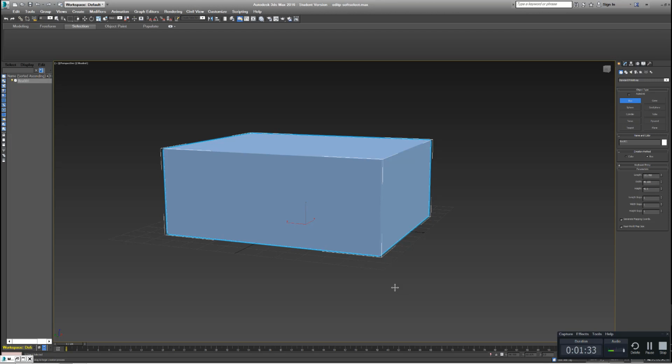So let's say you're animating a series of objects and you don't want them to intersect. You might want to check if they're moving across each other within the top view or in the perspective view, that sort of thing. So just a little helpful hint: if you ever want to switch between the default viewport, just hit the Alt key and W.